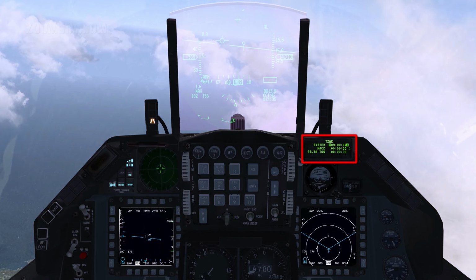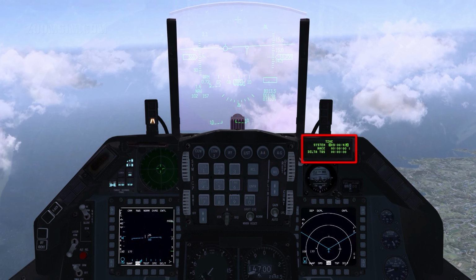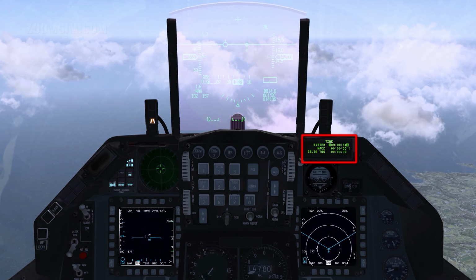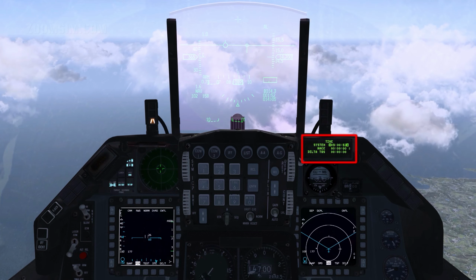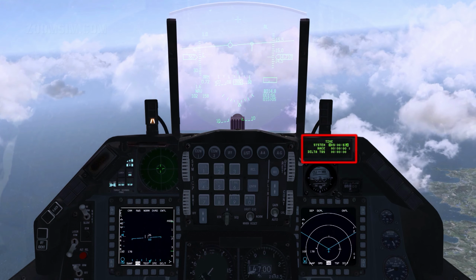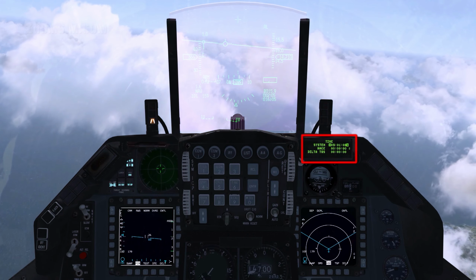To set a delta TOS, move the scratch pad to the delta TOS line, and to increment TOS for all Steerpoints, enter the desired value. For example, to add 2 minutes, enter 2, 0, 0 and press ICP enter. To subtract 2 minutes, first press 0, then 2, 0, 0 and press ICP Enter.